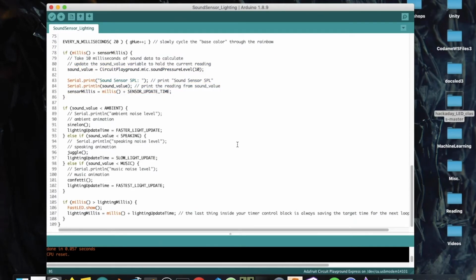You might want to slow it down even more or speed it up, so experiment with it and see how you feel. The value could depend on your mood. Do you want a rather static music detector with a value of around 600 to 1000? Or do you want a more reactive experience that might catch a sense of the beats it's hearing? If so, set it to around 100 to 200. Or it could depend on experimentation. It could even depend on the BPM of the music you're trying to light. Mess with this value for a few minutes and see what you like.